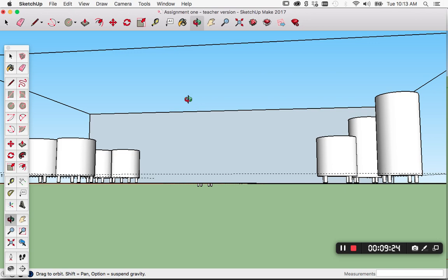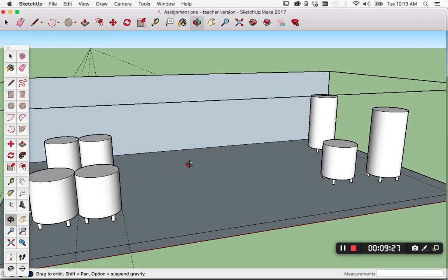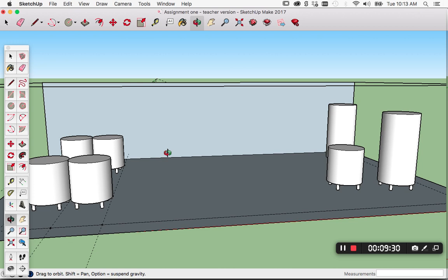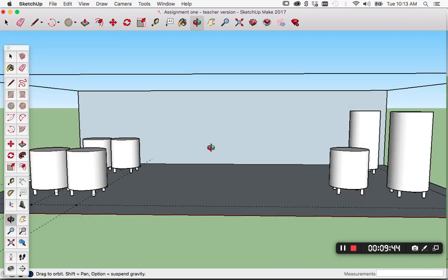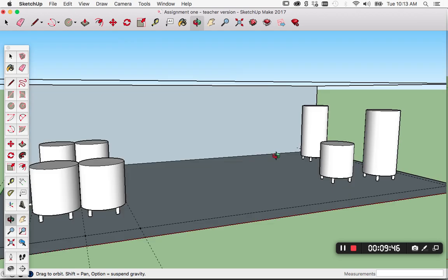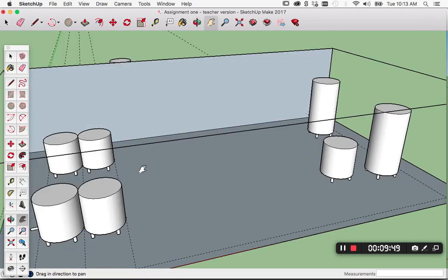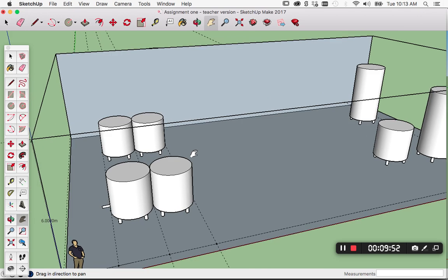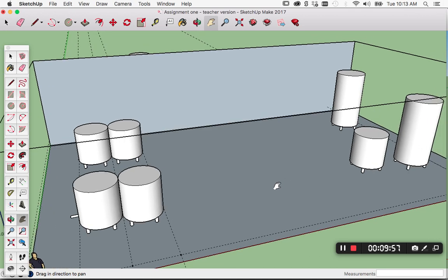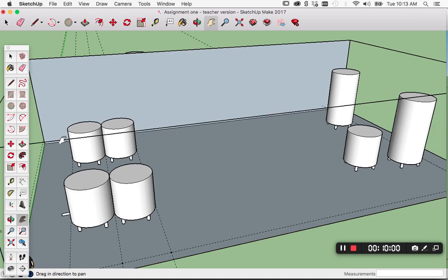The spreadsheet that I've provided you allows you to calculate the static head depending on the liquid level in the 2 tanks you're going to. So that's not in an ideal situation here where we know the maximum static head. So it's useful for that, but really for this exercise we know what the maximum static head will be. For both transfers it'll be 4 meters. So when we're doing the fixed line and the flexible line, we need to know the length of hose required. So we're going to come back here after we look at the spreadsheet and actually estimate the amount of hose required.